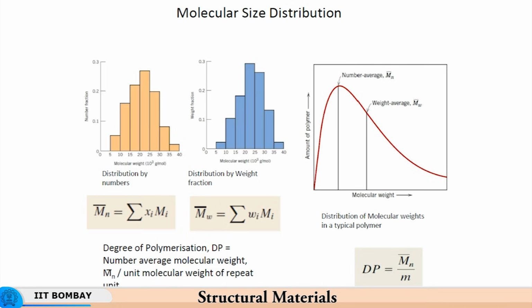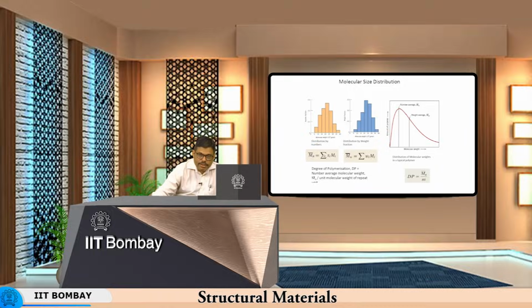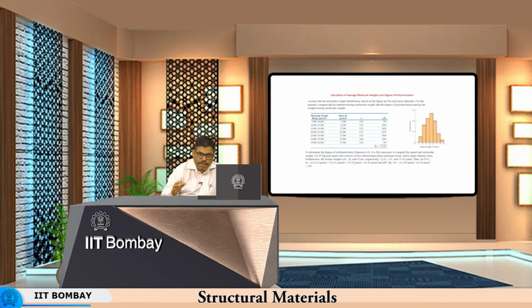Now, if the degree of polymerization is more, the molecular weight is more, and therefore the melting point is more, the strength is more. So, everything is correlated with the degree of polymerization. If it is just a monomer, there is very little strength, but if it has got polymerized over thousands of units, then the strength builds up, and particularly if it has got cross-linked, then it is even more. So, basically it is important that one investigates the properties from the structural point of view.